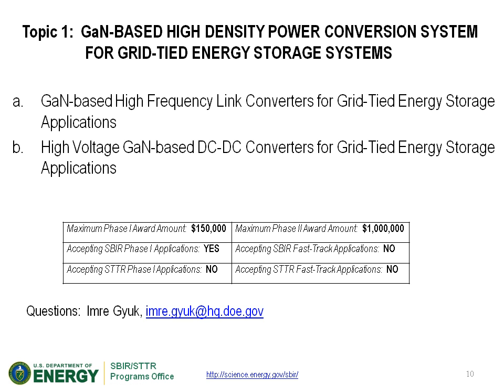So therefore, we have a higher power density design, but they have some challenges. There's a lack of good insulating gate oxide materials to date. They have low breakdown voltages, and the device stability and reliability continues to be an R&D topic.